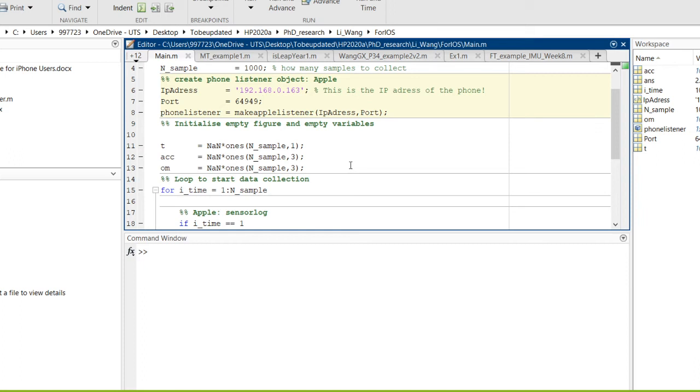And the third, for fall detection, there are several ways, but you can use at least one way to get the fall detection. The first is based on the analysis, the theory behind it. If you have no other acceleration, only gravity, then if you square the three components x, y, and z together and take the square root, it should be exactly 1g, no matter what direction you exercise. This is normally the case. That means zero acceleration.